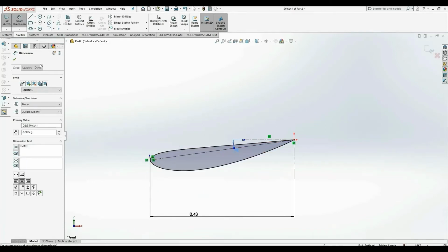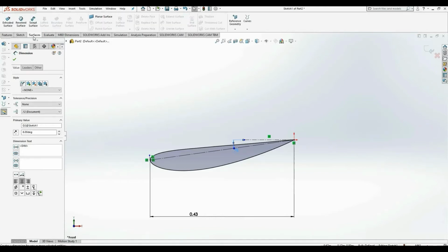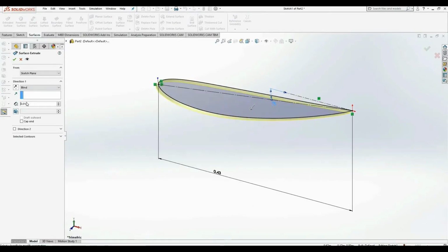This will be a changeable dimension as always, so we can change the angle of attack quite simply in the initial sketch, and that will allow us to reproduce that throughout the whole model, so we can do multi angle of attack analysis at a later date.